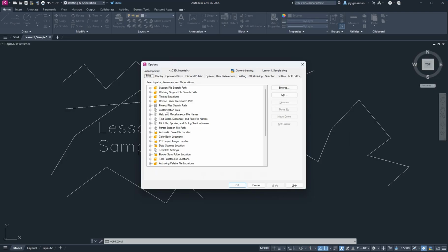If you want to dig into it and change where you're saving your files to, just FYI, AutoCAD auto saves every 15 minutes, or should be set up to auto save every 15 minutes. So if you're doing a lot of work and all of a sudden it crashes and you think you lost your entire file, you probably only lost 15 minutes. And if that happens in class, I can show you where to find the backup files for it.